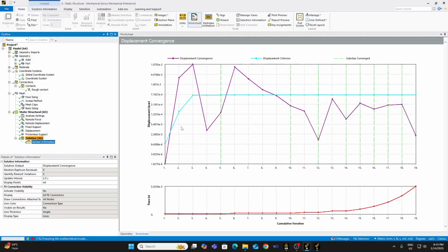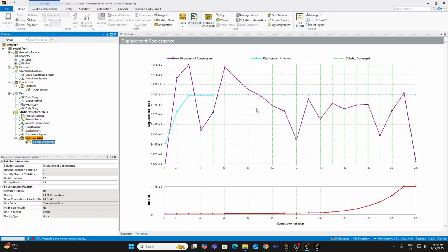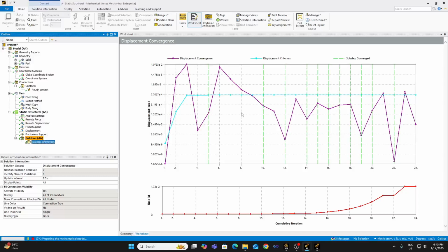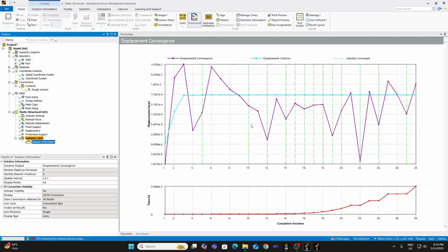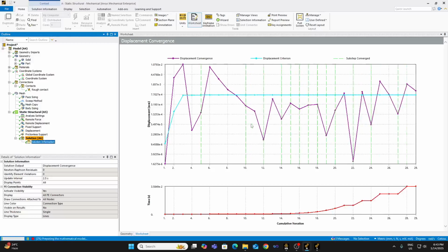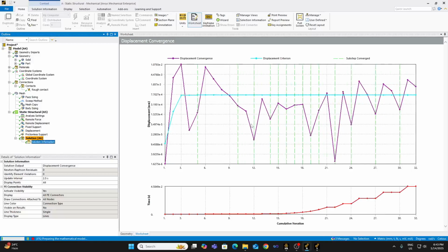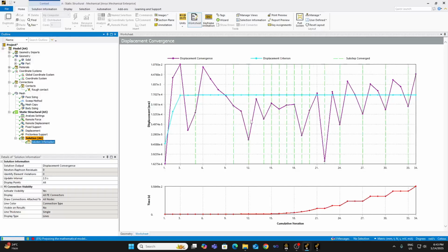You'd see that the initial couple of sub-steps take a bit of effort to converge. It's because initially the contact area is 0, because it's a point contact, and as soon as the contact area becomes finite after a couple of iterations, and also the initial time step size was of the order of 10 to the power minus 4. So when the load is properly applied and there is a certain amount of deformation and the indenter slightly sits on the specimen, the contact area increases, and thereafter the convergence becomes standard. There have been some smooth convergences over there.